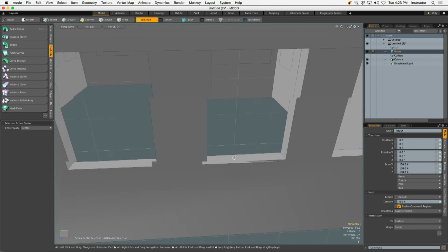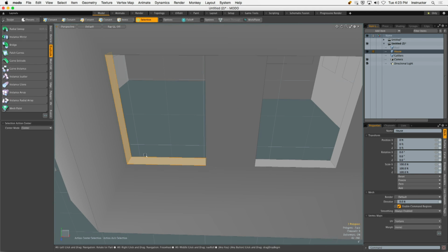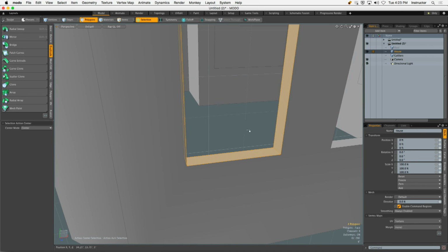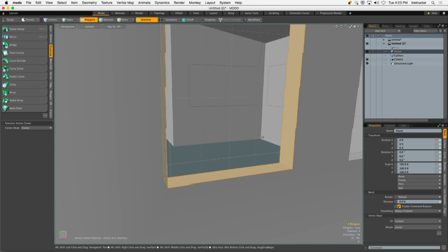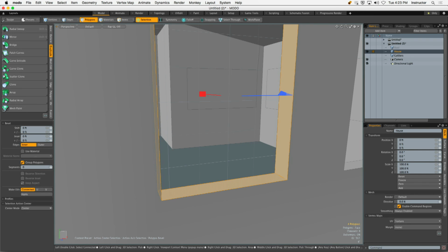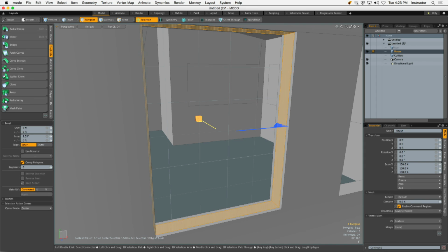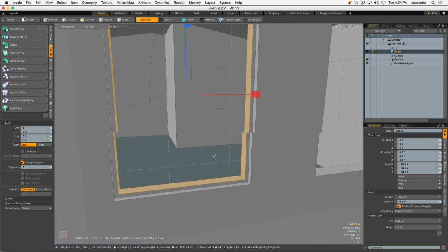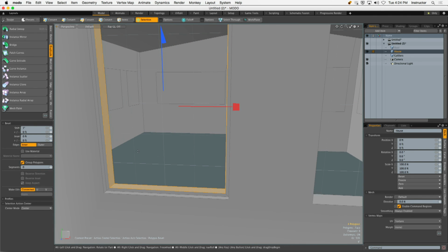Okie dokie. So here's what we need to do. I want to focus my energy on this one. Okay. What if I grab that loop in there and I start beveling it a little bit? Okay. Bevel it in. I'm even going to use real-world measurements here. I've just beveled it an inch. Okay, hold down. Let's do, that doesn't quite look enough to me. Let's do 2 inches here. 2 inches, that looks like it's too much. Let's split the difference, 1.5 inches. There we go. Hold down Shift, click. Then do a little bit of an offset here for an inch. Looks pretty good. There's the frame of the window.